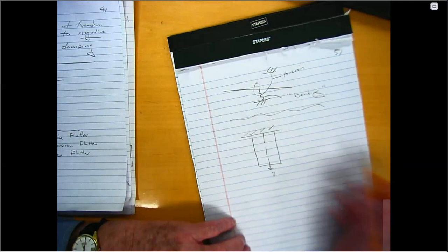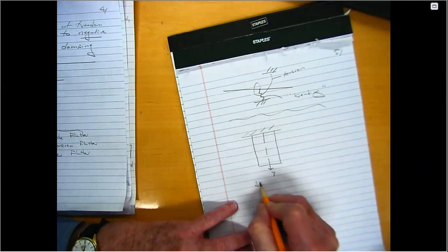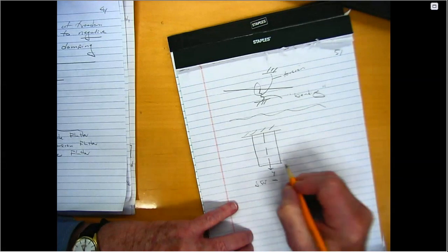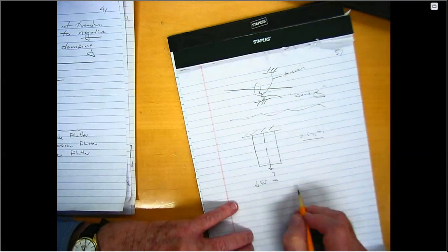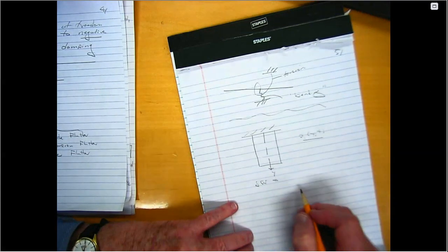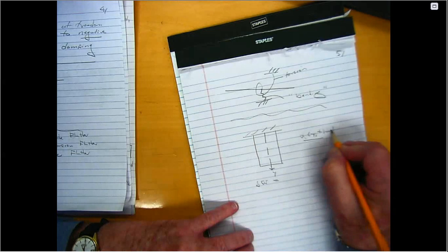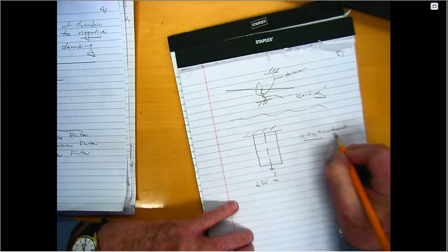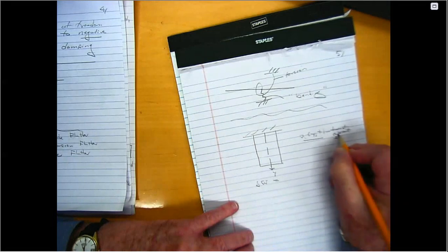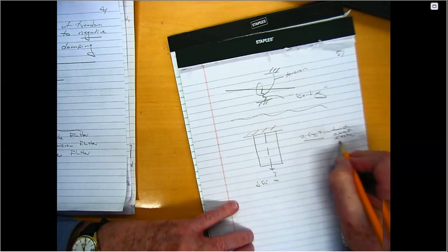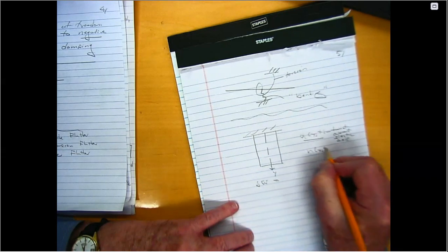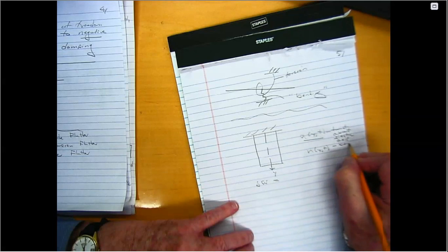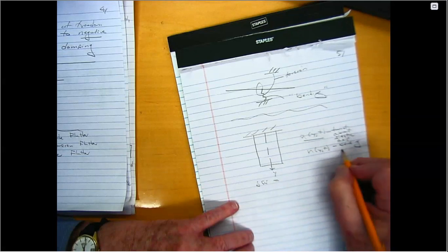I'll do the easy one first. Virtual work. Let's see, alpha of y and t, we're doing dynamics, right? So alpha depends on y as well as t. That's the twist about the elastic axis. And h, which depends on y and t, is the bending, or if you will, the translation of the elastic axis.